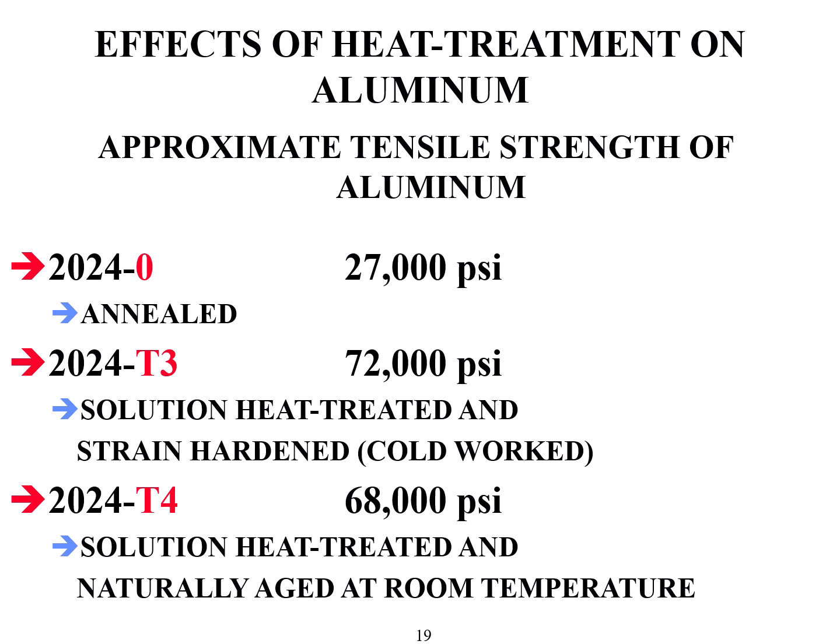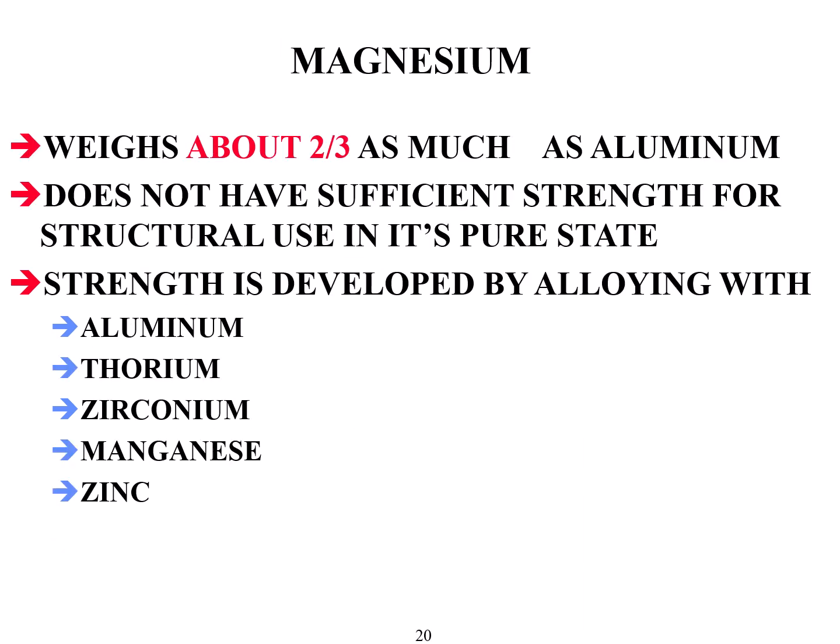If you use the wrong material in repair, like these two, you have not completed an airworthy repair. You subject the airframe to possible damage and the people to possible injury or death. So reading those data stripes, knowing you have the right material, is a very important part in selecting material to make repairs with.